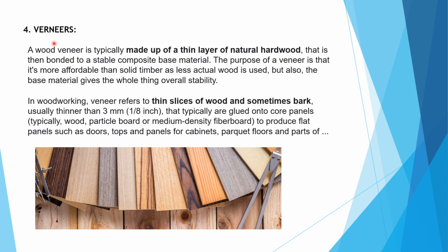Next, veneers. A wood veneer is typically made up of a thin layer of natural hardwood that is then bonded to a stable composite base material. The purpose of a veneer is that it's more affordable than solid timber, as less actual wood is used, but the base material also gives the whole thing overall stability.